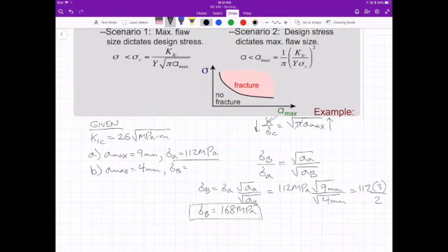So like I said, the toughness of the material is the same, because it's the same material, but by decreasing the void length from 9 millimeters to 4, we've increased the strength of the material 150%. So a lot of it comes down to how good we can process, how we form our final material. If we do it very cheaply, very quickly with large voids, you're going to have much lower stresses that the material can handle. If you put in more time, be more careful with your forming, you can get the material to increase its strength quite dramatically.